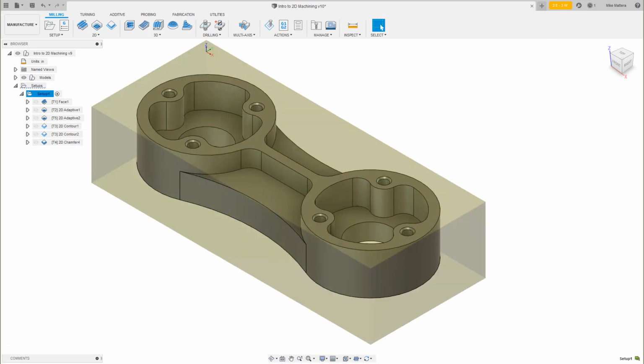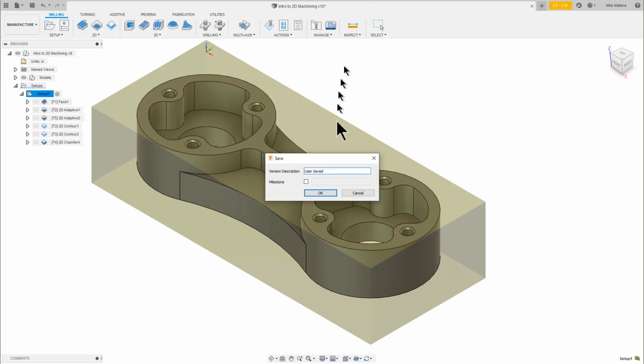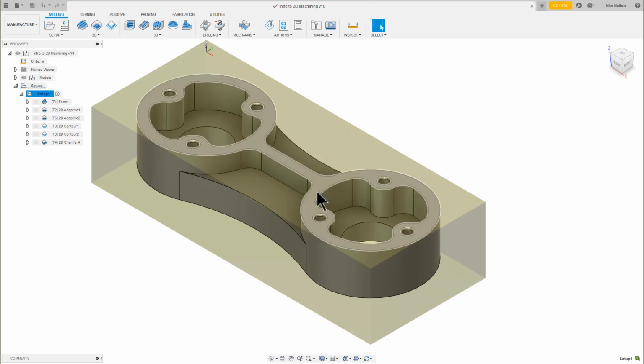In this lesson, we learned about how to break all the sharp edges of the part using the 2D chamfer toolpath. We made some adjustments to the lead-in, lead-out parameters and learned how to turn off the model display. Press Ctrl+S to save the part, Command-S on the Mac.